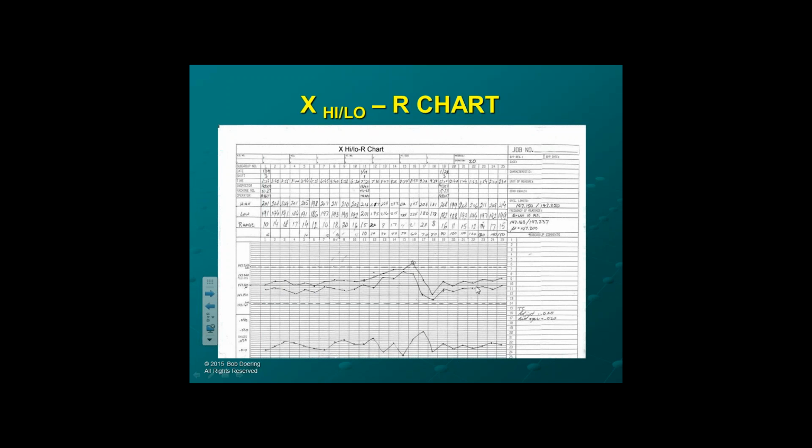Now, just like you would expect in real SPC charting, when you make an adjustment, you should mark what that adjustment is. That way you know that this process didn't do this on its own, because it could, and that's not a good thing. You want to know when there's a shift that it was an intentional shift. And in this case, you can see that because they told you on the chart that they made that adjustment, and that's good.